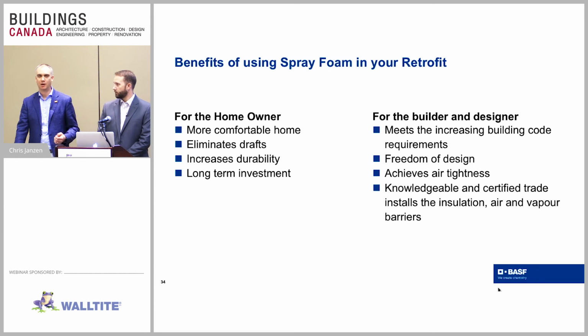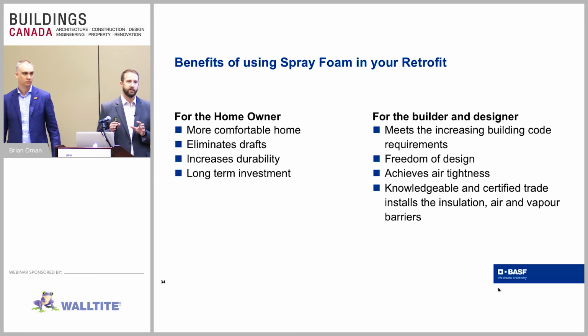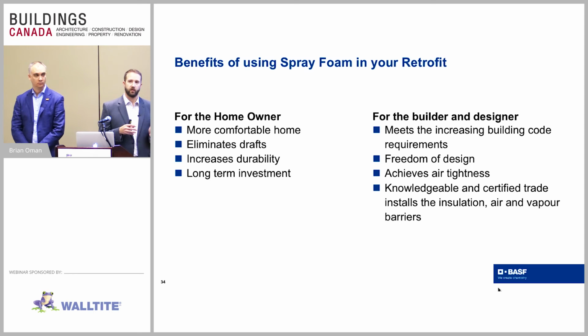A lot of it comes down to making sure the building is properly built and properly dry, so that the studs don't have a high moisture content. That's why you want to use a certified installer to make sure they're installing the product properly. That's the big one I would bring up: the installer. Medium-density closed-cell foam has a certain level of flexibility. It's a urethane, so for those familiar with other urethane adhesives like Gorilla Glue, it's going to bond extremely strongly to what it's been applied to.